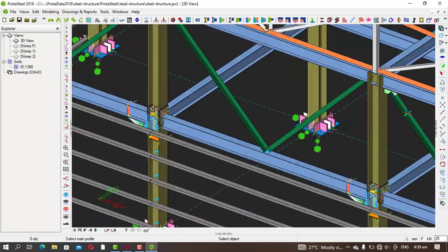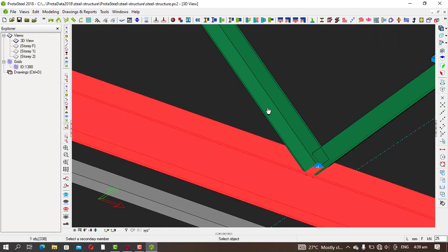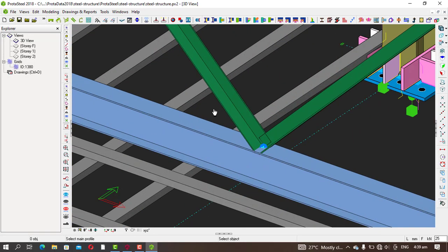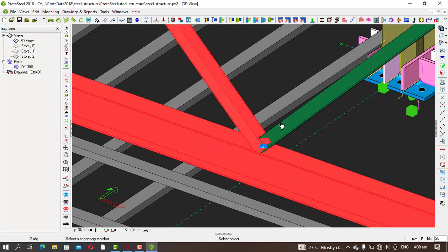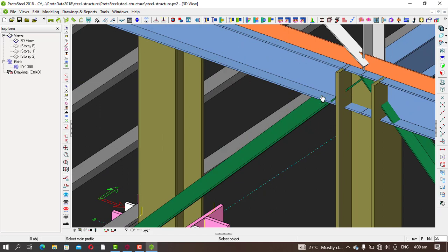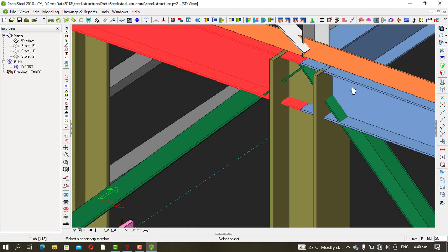So here you have a bracing tool. Select this, right click. And then here too, select this, right click. Then here you can use these three because you only have one bracing. Now, if this is a straight beam, then you can say you have two bracings at that point. But you can see this is not a straight beam, this is a separate beam.